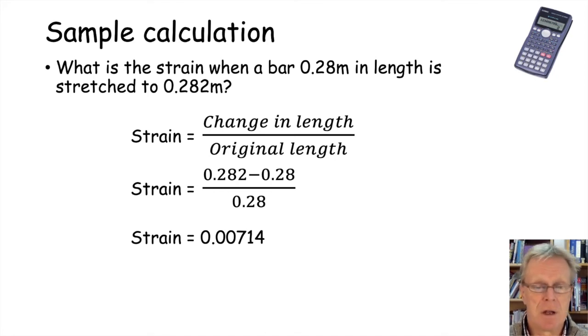And as I say, normally the strain numbers are pretty small. And if you're asked to calculate a strain in a piece of steel or something and it comes out at 10%, you probably dropped your power of 10 somewhere or something like that.